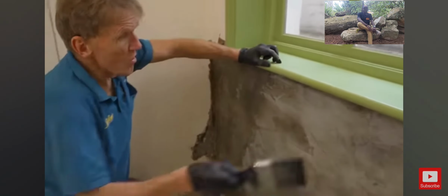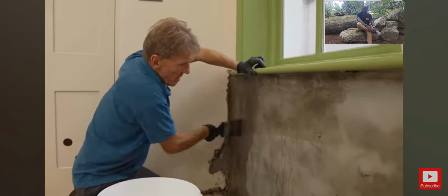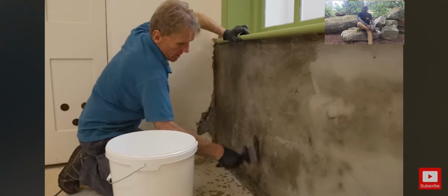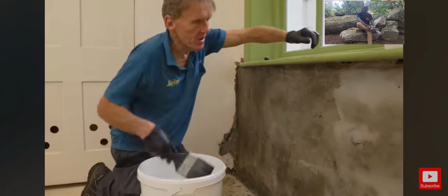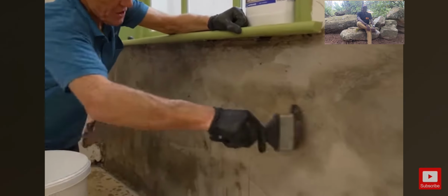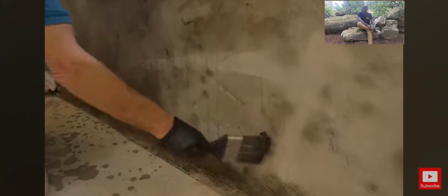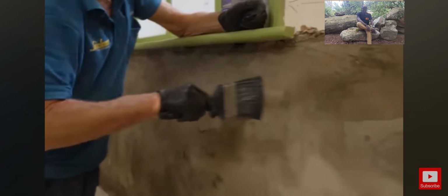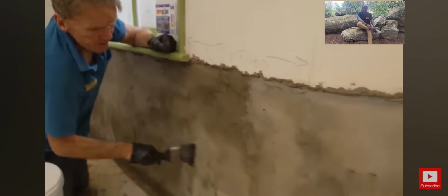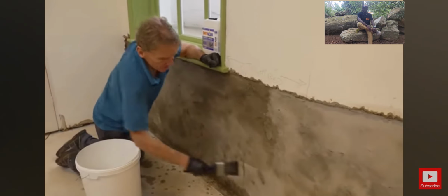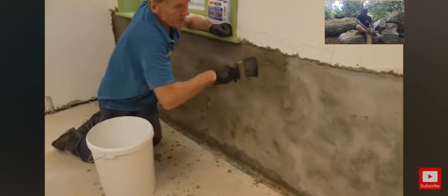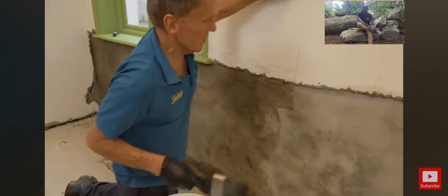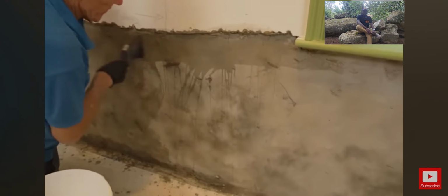Now, it's quite a warm room I'm working in here, unfortunately, because I've had the underfloor heating on for a week or 2, but hopefully with this, I won't be chasing it too much. I've turned the heating off now, giving me a fighting chance, but we'll see how it goes. The idea is I actually want to put 2 coats on in succession. So 1 coat, then a couple of hours, let it firm up, and then follow up with the 2nd coat. And that will make sure that there's no little gaps that we've left anywhere.